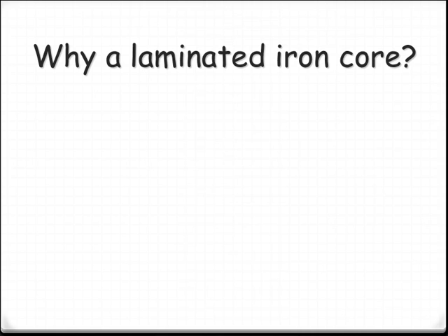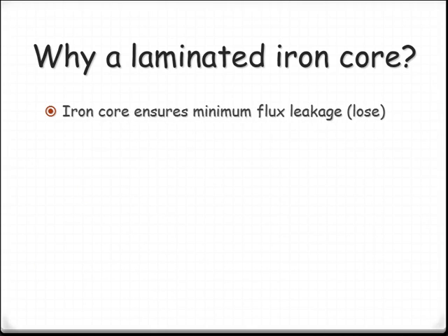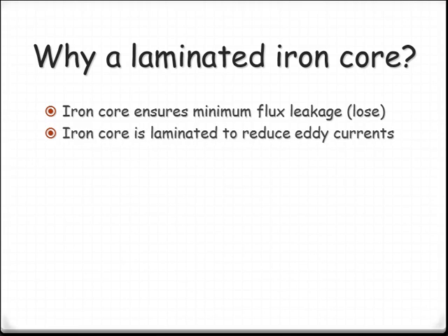So why the laminated core? I mentioned something in class about this the other day, and it's totally to do with ensuring that we minimize the amount of loss of flux that's passing through. It avoids or reduces eddy currents forming in there, and that's really all you need to know.